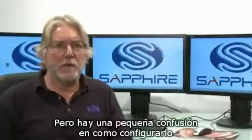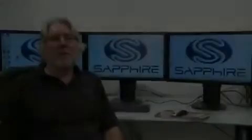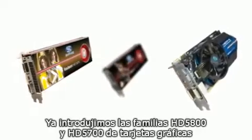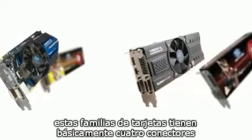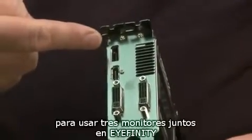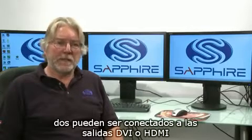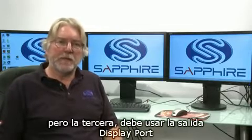But there's been a little bit of confusion about exactly how it's set up and what you have to do to make it work correctly, so this is what we're going to run through today. We've already introduced the HD 5800 and HD 5700 series of graphics cards which support this Eyefinity technology. Those series of cards basically have 4 connectors on the backplate of the graphics card, 2 DVIs, 1 HDMI and 1 DisplayPort. To use 3 monitors together in Eyefinity, 2 of them can be connected to the DVI or HDMI outputs, but the third one has to use the DisplayPort output.